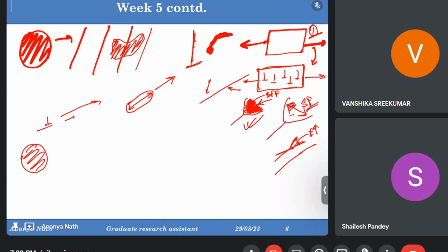So as soon as the furnace cools down, only then will the material cool down. So annealing takes a day-long time. But for normalizing, we keep the material in the normal open environment, in air. So it's basically air cooling. We similarly heat up the material up to the recrystallization temperature, and then we let the material cool down under air. So these three are very important.